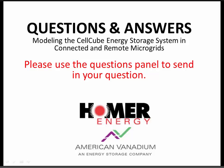And also, we're dealing with new technologies, and just like all new technologies, we're on a declining cost curve. So the danger is that by using a single dollar per... we can't use dollar per watt, as we've mentioned. So the next thing that you would look at is maybe a dollar per kilowatt hour number. But those are very non-linear, so there isn't one magic number that would go across the board. The danger is that you carry that number around in your head and you try and apply it to a system that lasts for 4 hours or 8 hours, or that's 1 megawatt big or 10 megawatts big. There isn't just one number for that.